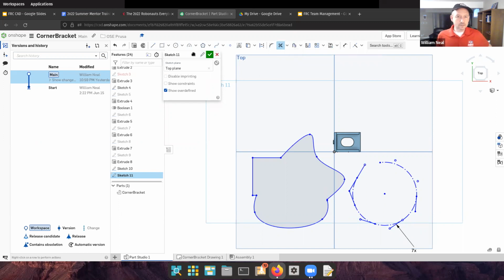And now you see some of these tools also have a drop-down menu. I can make a corner rectangle or a center point rectangle, and that just determines how the shape is formed with my mouse. I can also align the rectangle at a certain angle. So you can explore these drop-downs. It can be a circle you're making starting at a center point, or a 3-point circle if you're a math person, or an ellipse if you really just like different shapes. And same with our arcs and our polygons and our splines, there are different options that you may use to make your 2D sketches.